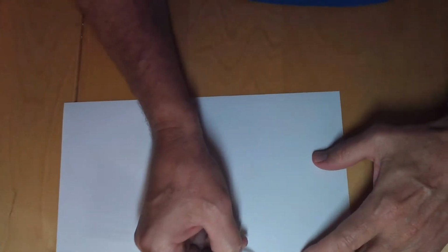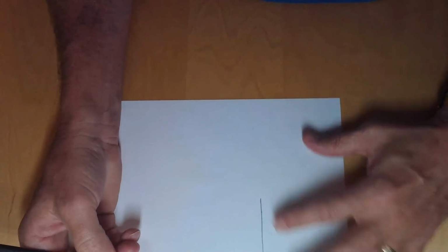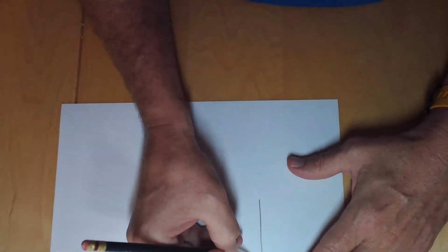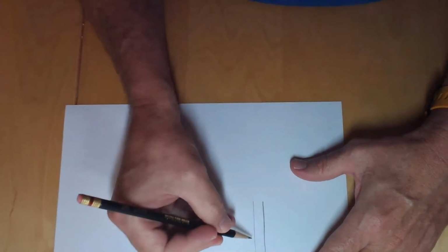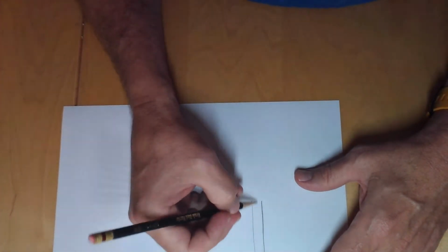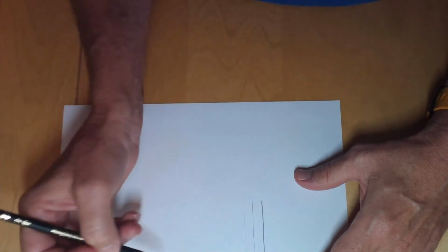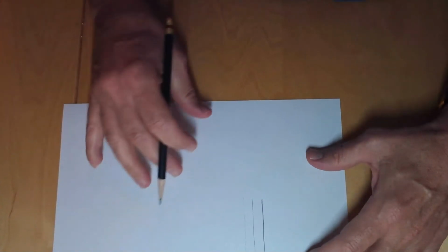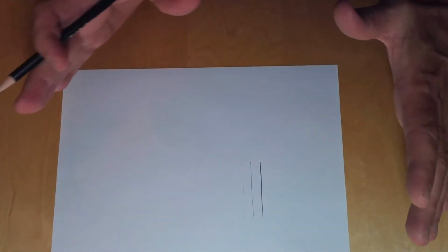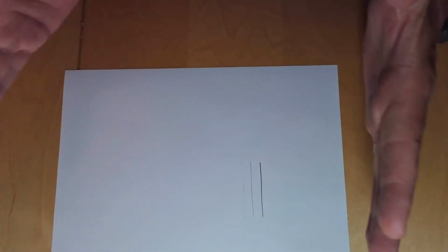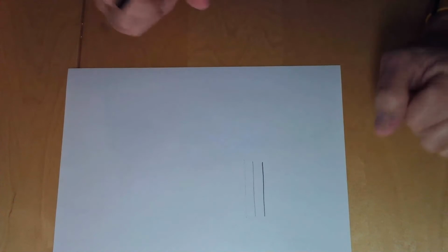A thick line is going to be a nice, solid, straight line. A thin line is still going to be visible, but it's going to be thinner, lighter than the solid dark line. A construction weight line is just going to be a barest whiff of a line, something that you can barely see when you're looking at it. The important thing here is to understand when and how to use these different line types. You're always going to start with construction weight lines.